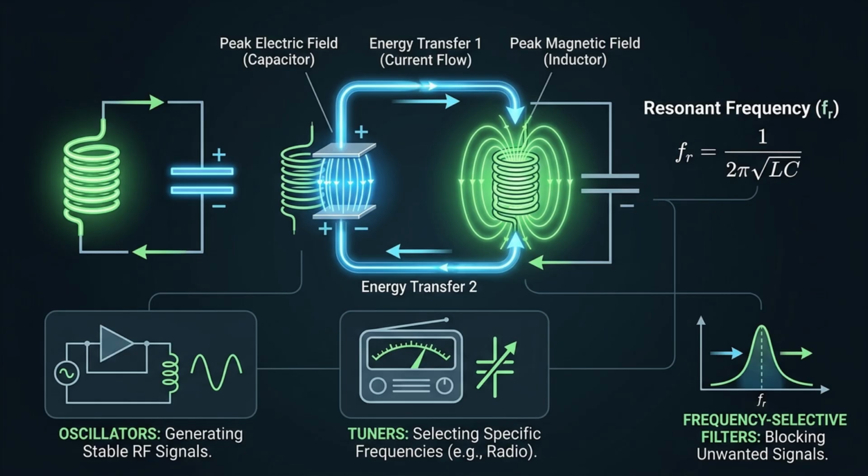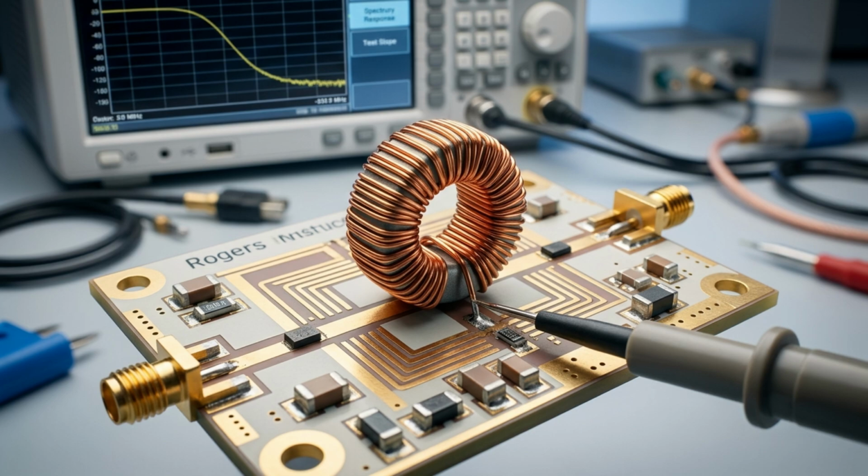Inductors are also key components in resonant circuits, where they interact with capacitors to define natural oscillation frequencies. These LC resonance structures form the basis of oscillators, tuners, and frequency-selective filters used in communication systems. Understanding inductors is crucial for RF engineers because many high-frequency behaviors are dominated by inductive and capacitive effects rather than simple resistive behavior. This makes inductors a foundational element in both circuit theory and real-world RF system design.